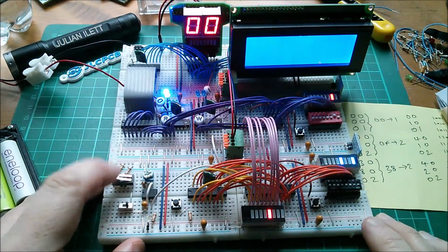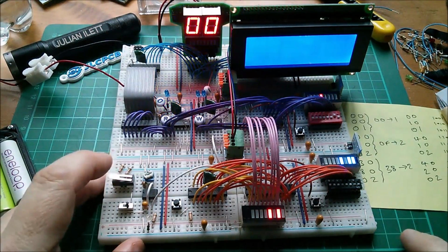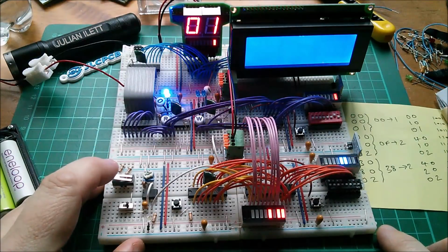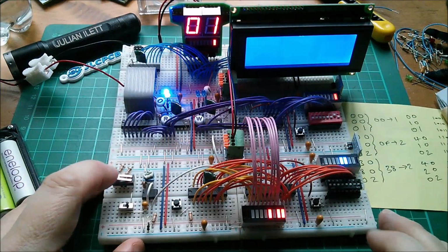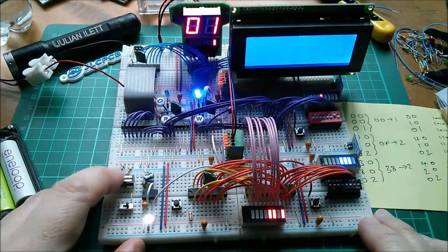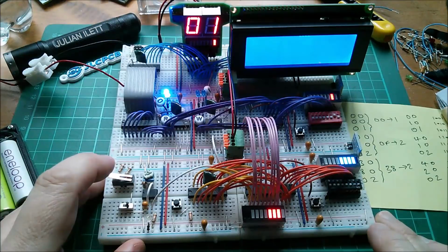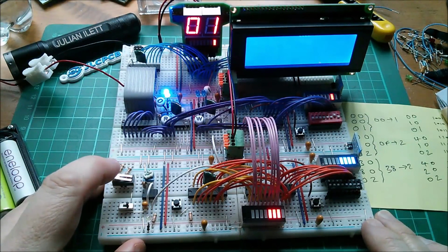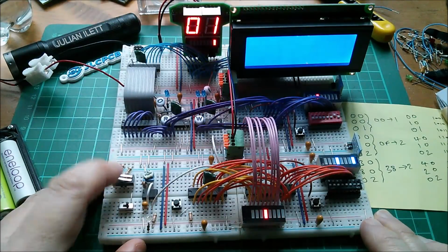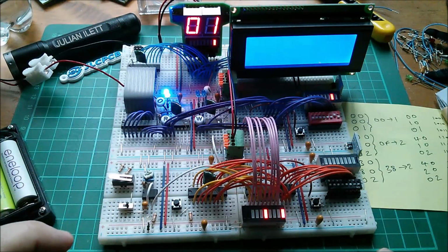Okay, let's carry on. 0 0 1 0 0 1. This should be putting data in now. Oh no, that just sets the register selector the other way, that's right. And then 41 0 2, that should put something on the display. Oh, it has, but the contrast has gone all weird. Let's do the final 3 steps. Yeah, that's worked, but I don't know why the contrast is weird.